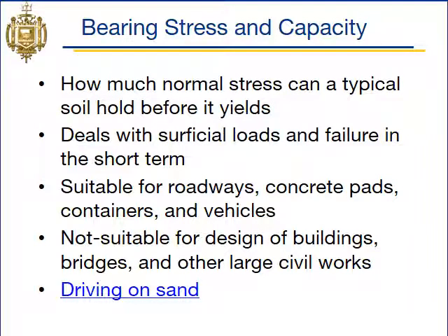So what is bearing capacity? Bearing capacity and bearing stress is how much normal stress a typical soil can hold before it yields. Bearing stress and capacity deals with superficial loads, so loads very near to the surface and soil failure very near to the surface.